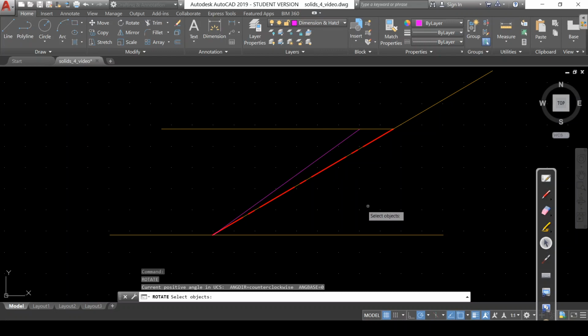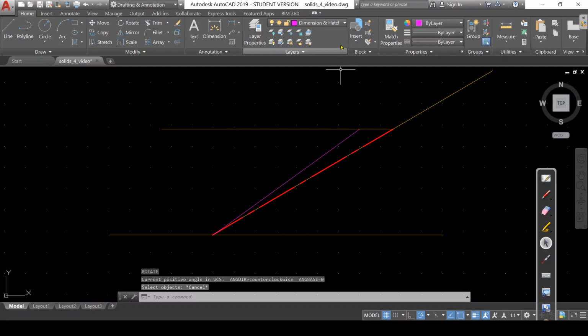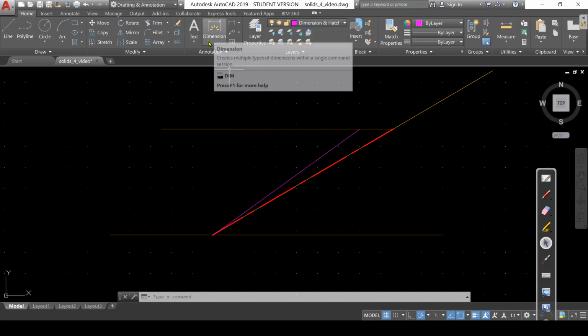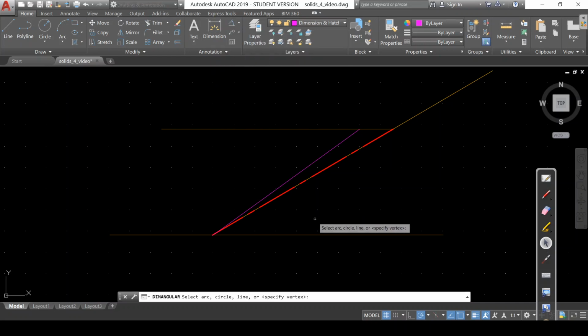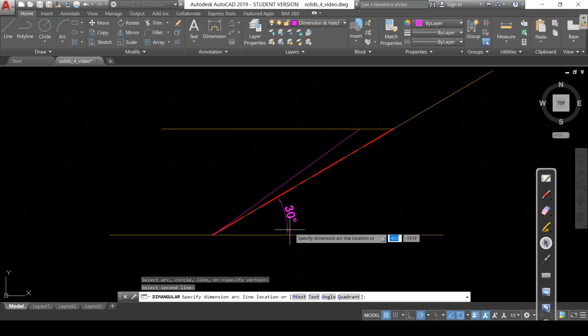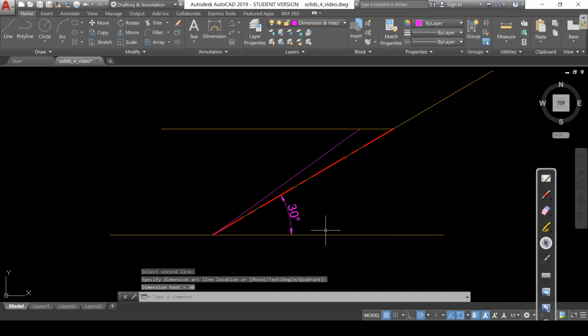If you want, you can measure these dimensions as well. So dimension and hatch is already there. So just give this angular dimension here. See, this is the true length of the axis, making true inclination with XY line. Okay. And now what is the apparent angle? We don't know, but we have marked that now. This is the concept used. This concept we have used from projection of lines.